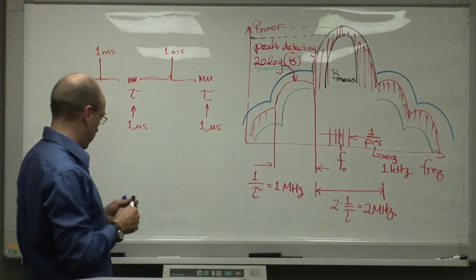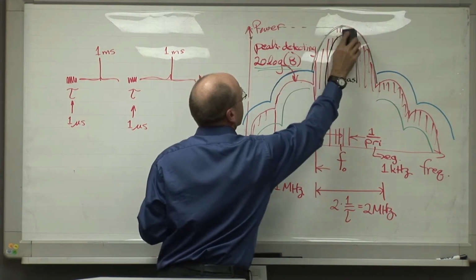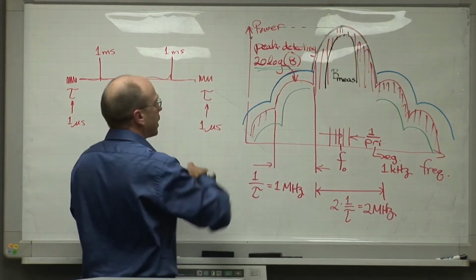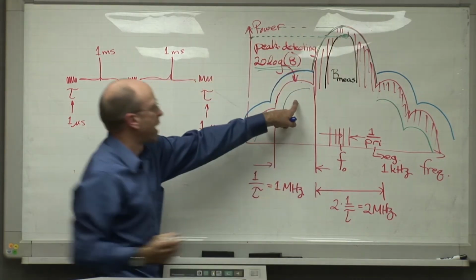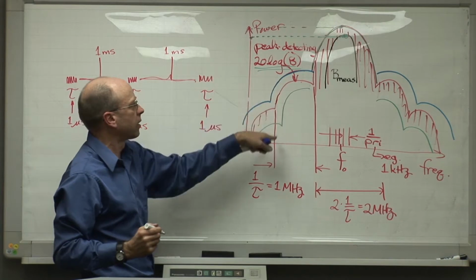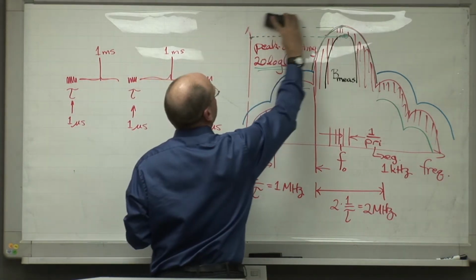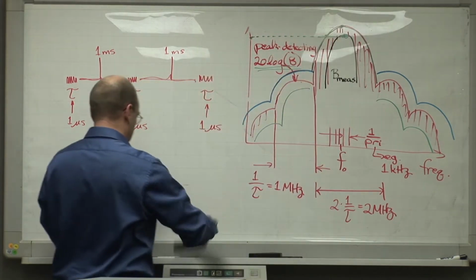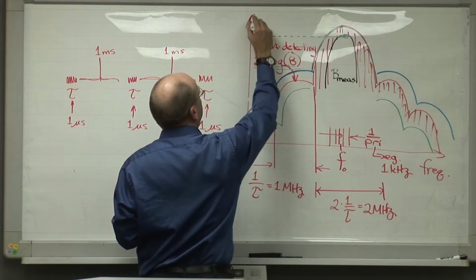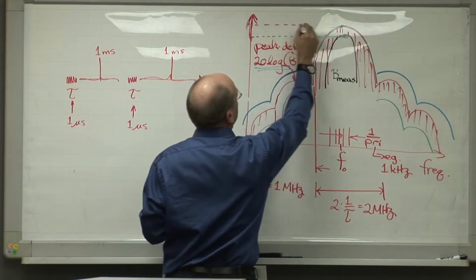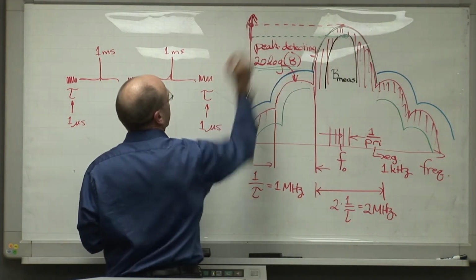And when we do, we get a power level that measures out like that. I'll color code this. I'll make this one green, to show that this was the power level that we measured with this narrow bandwidth right here, where the power level in this part of the spectrum was down in here. There's our green. Then we come to the red, which is the power level that we measure in a matched filter bandwidth, which matches about 1 over the pulse width of the radar, in other words. We measure this power level right here.